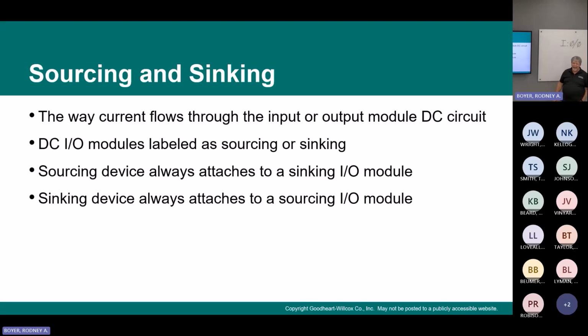Sourcing and sinking. This confuses a lot of people. A sourcing device always attaches to a sinking I/O. A sinking device always attaches to a sourcing I/O. It's all about the way that the current flows through the input or output module in a DC circuit. They are labeled sinking and sourcing.